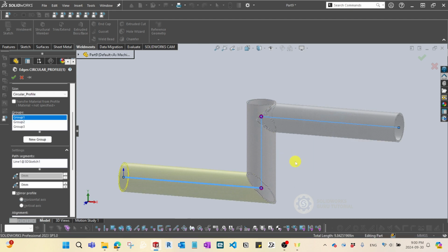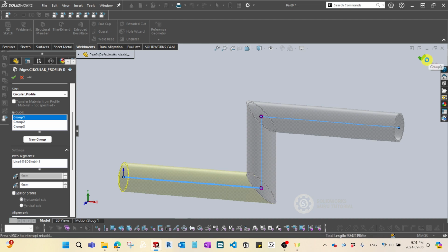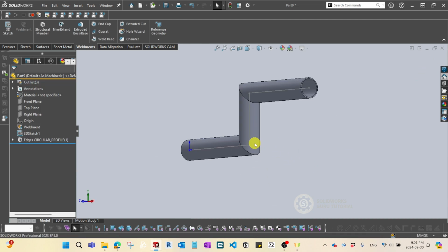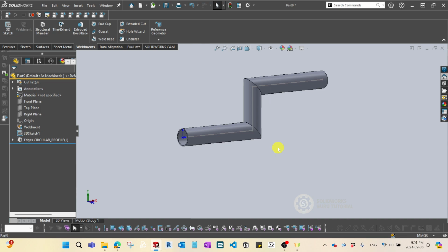All right, and then what I want to do is also do the same thing for it. So I want you to click and then which one is the point. This one's supposed to go second option, which is corner blocking. And even for the second one, if you click down arrow, it's going to be open, but I just want any point open. So just click OK and then hit OK. So yeah, perfect. That's exactly how we treat the corner points, and all the options are very limited for users, so it's so straightforward and easy to choose the applicable cases.